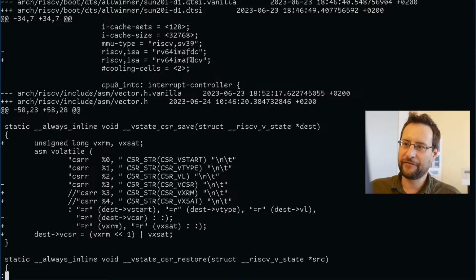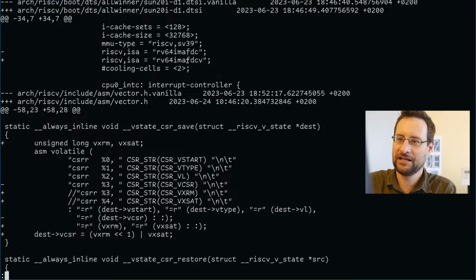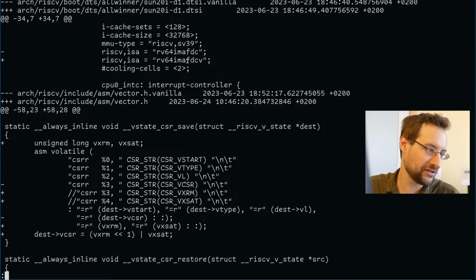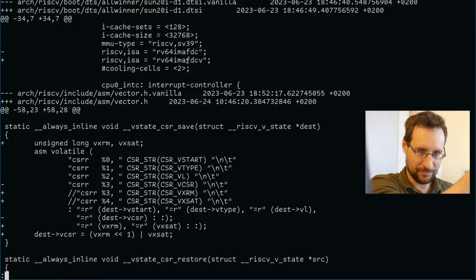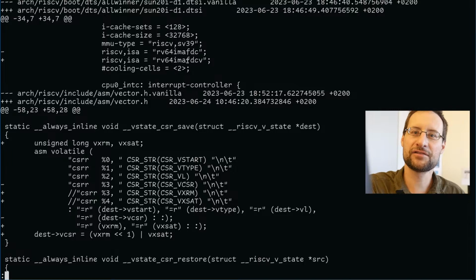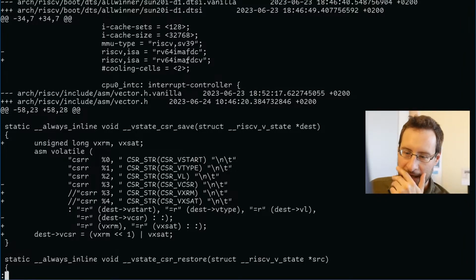The RISC-V ISA string is hard-coded in the bloody device tree. It's like I have no words anymore. I was working on this stuff, wondering why the vector extension does not enable and come up, until I realized they hard-coded it. That is not Allwinner stuff, that is Linux platform enablement device tree at its finest, if you were wondering why I still dream about my unsuccessful little microkernel.